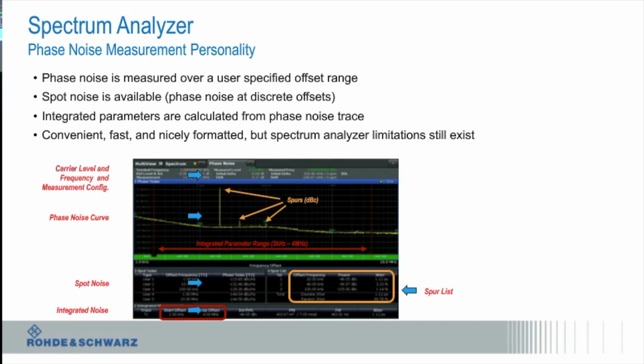So that curve I showed you that had the different graphs, if you are above that curve, it knows that it's phase noise. The way it does the measurements, it does it with I and Q as opposed to just an amplitude detector. So it has a lot of ability to determine between phase and amplitude variations. But that's the limiting factor. If you want to go below that, you will run into that limitation. But then you would go to a phase noise analyzer, which is specifically designed to measure phase noise.